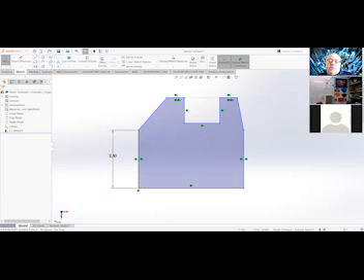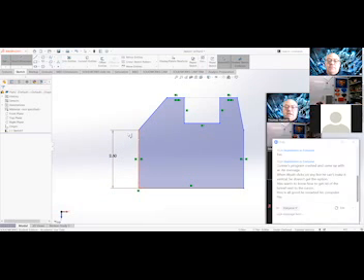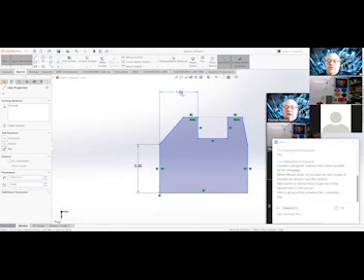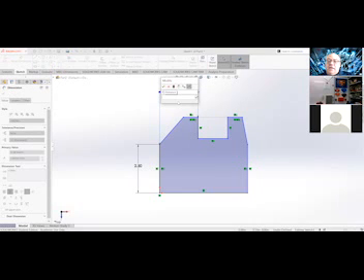So if we remember from our drawing, we have a part that is 9.33, and that was across the edges at the top. So I'm going to do a smart dimension. I'm going to select the first line, that's the vertical line that's black, and that's going to go to the next vertical line. So right on over to this point. Notice it'll highlight orange before you select it. And I'm going to bring that value up. And this value needs to be 0.933.